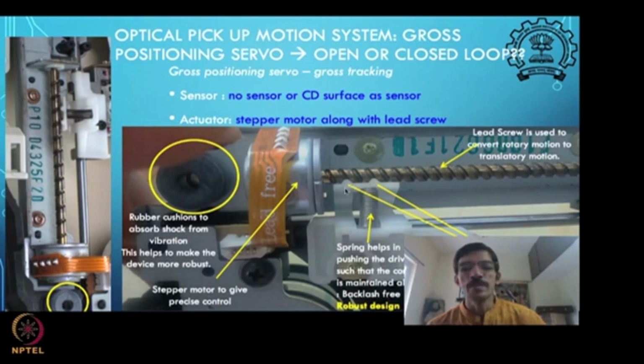And this mechanism is useful for preventing backlash. You heard this term, backlash? See, if I have only, for example, one tooth going into these slots here, then, because of manufacturing tolerances and errors, the slot size and my tooth size may not match perfectly. Within some tolerance accuracies, a few microns, it will not match. That means I'll have that much back and forth motion around in the slot.